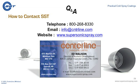Okay, next question. Must the angle of the spray be 90 degrees at all times to the surface? Not necessarily. Of course, we've done so many studies on this because Centerline over the past 10 years has gotten requests to cold spray parts or components that are in areas that may be extremely challenging to access, accessibility issues. So we have to design 90-degree nozzles or 70-degree nozzles. Here's the rule of thumb that we know for sure. We prefer that the customer spray 90 degrees perpendicular to the surface. You can vary that by 10 degrees off perpendicularity, so plus or minus 10 degrees.